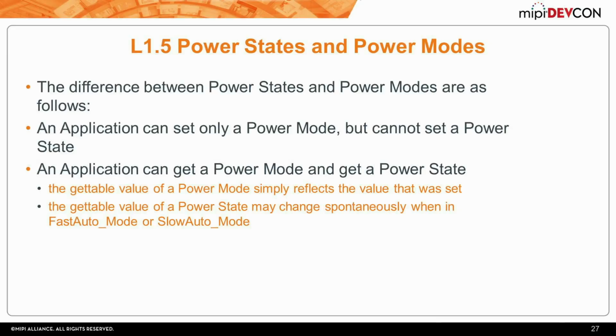So there's a difference between power states and power modes as well. So an application can set a power mode, but it can't define a power state. So the power states are the M-PHY states at the lowest level. So depending on the mode, the layer 1.5 manages this power request between the upper layers and the physical layer.